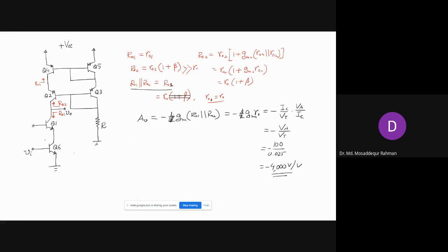So here you have the bias voltage. Now, what is this one? Q1, Q6 together, what do they make? This is a cascode amplifier, right? Yes, sir. Right. Cascode amplifier, and you have the cascode current mirror as the active load. Now, cascode amplifier with cascode current mirror.